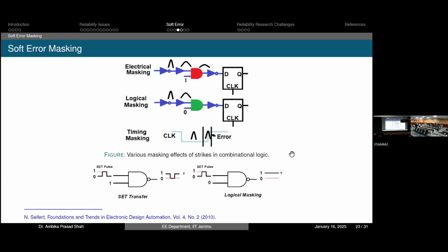But we know that the time period of the levels is more than the transitions. So if you want to avoid that, use the edge trigger instead of the level trigger. If you are using the edge trigger, this impulse will only be transferred when there is an edge, or your spike is coming at this point of time. So this is one of the ways by which you can avoid it.